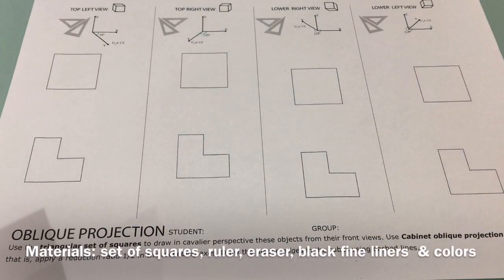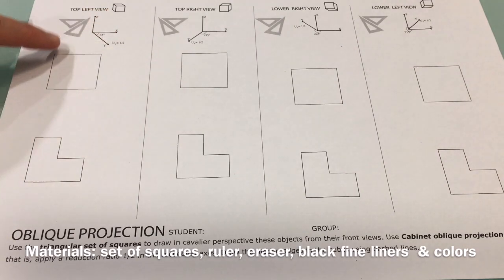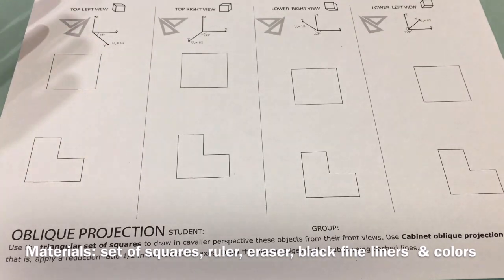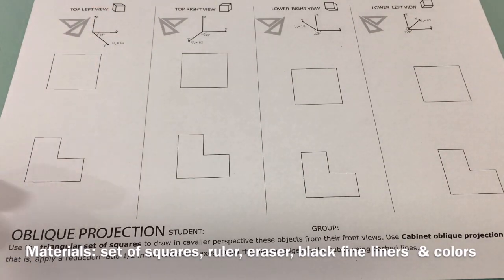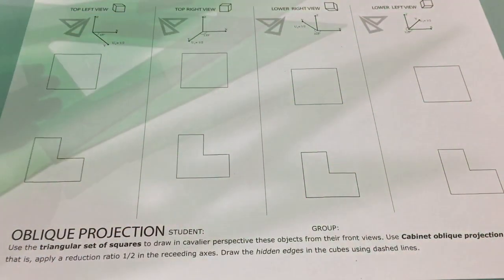The first thing we will do is to take the triangular set of squares to start constructing the axis. We will reproduce the axis given on the faces of the cube. So this is going to be the rear or back face of the cube. We will construct the top and the right side of the cube and the front face. The position of the triangular set of squares is given, and this is how it works.